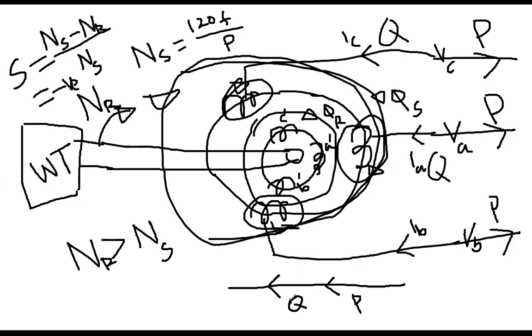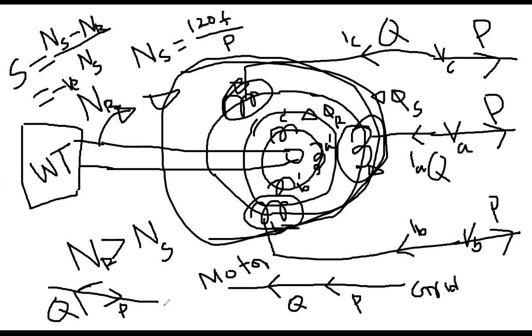So this is the motor power flow diagram in this direction. This means from the grid point towards the motor. This is the indicated direction of P and Q. But if it is a generator, see this one, as I said, the power flow will be from the generator to the grid. So the P direction will be this, but still the Q direction will be the same as the previous. Sorry, still the Q will be the same as the previous situation. Still the Q is this one, from the grid to the motor. Therefore, everybody see, when it is motor operation, Q is from the grid to the motor. When it is generator operation, it is still from the grid to the machine side. That's the difference, it is in the P.